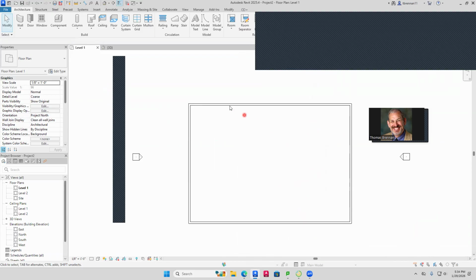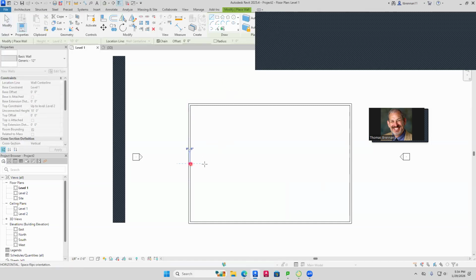Then I'm going to do a couple things here. I'm going to create another wall. I'm going to grab this wall, go from the midpoint here, and go right to there. When I do that, I'm going to undo that. Oh, by the way, Control Z is undo. I use a lot of it. Notice that when I hover the cursor here, it just gives me distance. But if I drag it to roughly the middle, do you see that triangle? That's your midpoint. You click on that, and that's exactly your midpoint. When I click over here, you see that's 35 feet on each side. So it really is trying to figure out what you want to do, and it's going to let you do that.